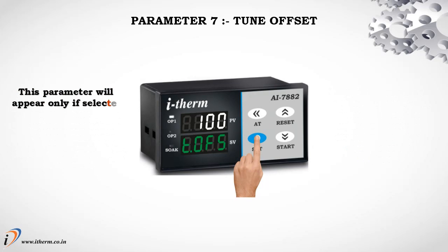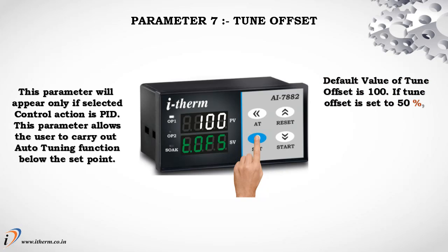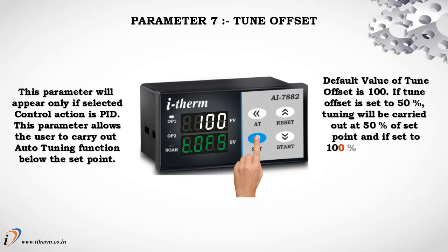Parameter 7, Tune Offset. This parameter will appear only if the selected control action is PID. This parameter allows the user to carry out the auto-tuning function below the set point. The default value of tune offset is 100. If tune offset is set to 50%, tuning will be carried out at 50% of the set point, and if set to 100%, tuning will be carried out at 100% of the set point.